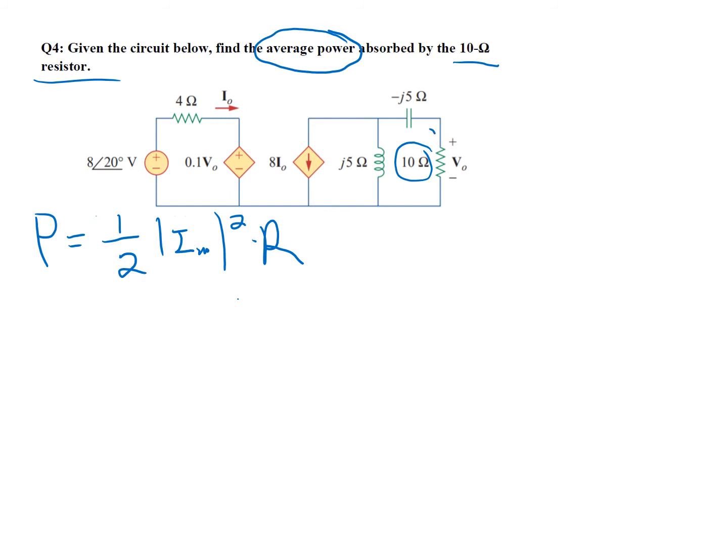To find the current across this branch, let's say that's Im, we first need to solve this circuit. To solve this circuit, let's recall, we don't have any current going through here. Let's say that's Ix is equal to 0. So we can separate this circuit diagram into two parts, the left part and the right part, and solve them separately. Well, let's first solve the right part.